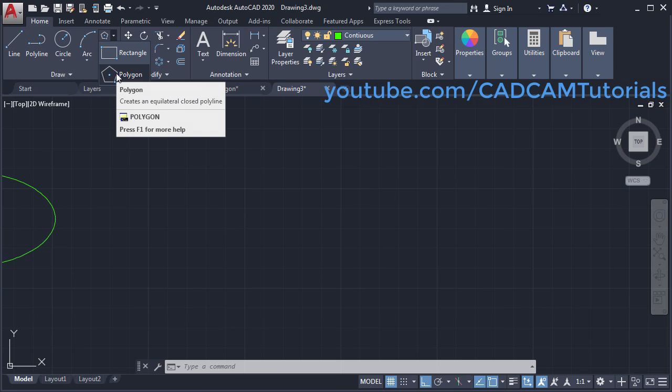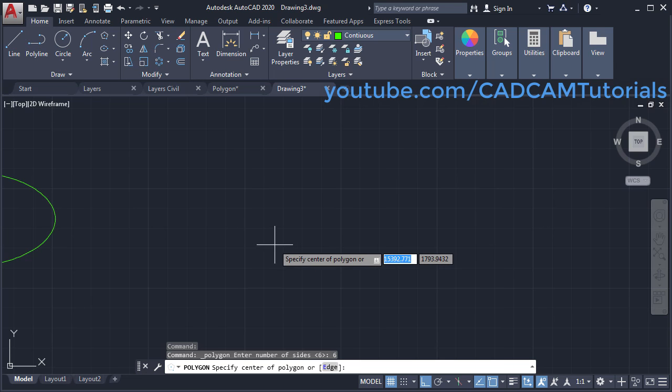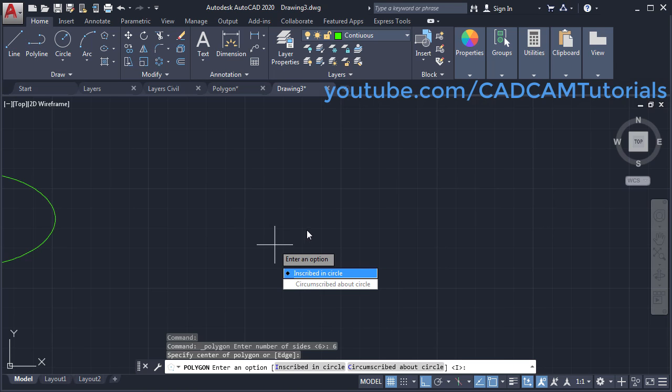So click on polygon. Then specify the number of sides. Suppose I will give 6 here. Press enter. Then specify the center of the polygon. Then suppose I want to create the polygon by the inscribed in circle method. Click on it.